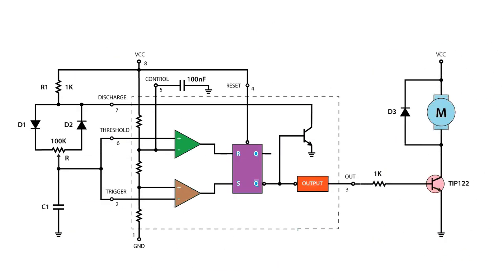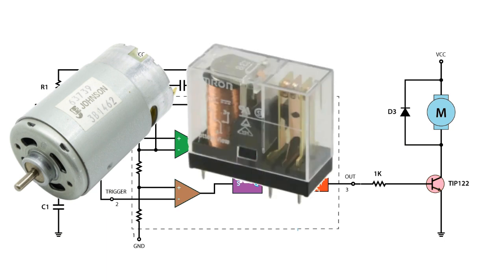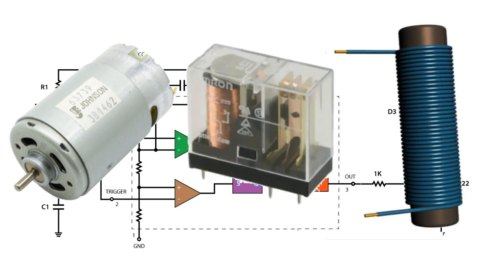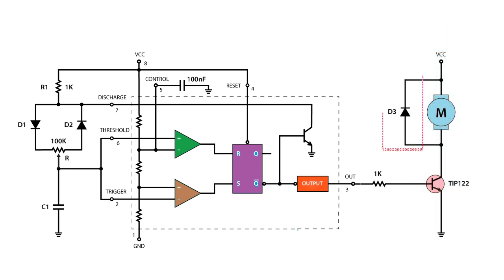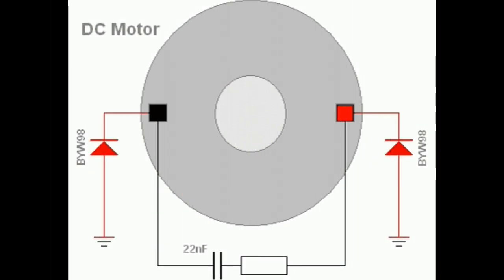The transistor in the two previous examples can be replaced with a power MOSFET device, or Darlington transistor, if the load current is high. When using an inductive load such as a motor, relay, or electromagnet, it is advisable to connect a freewheeling, or flywheel, diode directly across the load terminals to absorb any back-EMF voltages generated by the inductive device when it changes state.